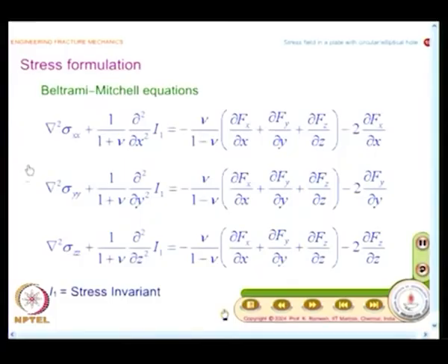forces. See, one of the important class of problems in solid mechanics is when the body force either remain constant or goes to 0. Whether it is constant or goes to 0, what way these expressions look like? If you look at very closely, suppose I take the case when body force is constant, none of these differential can exist, they will all go to 0. So, the right hand side of these expressions will go to 0. If you look at the left hand side, the equation is a function of the Poisson's ratio, you have to keep this in mind.